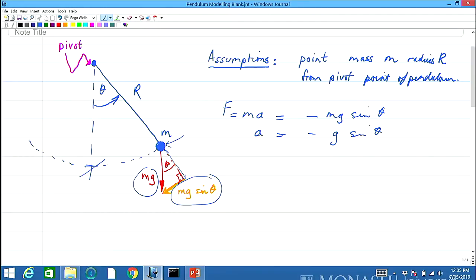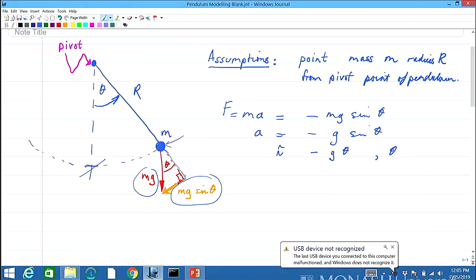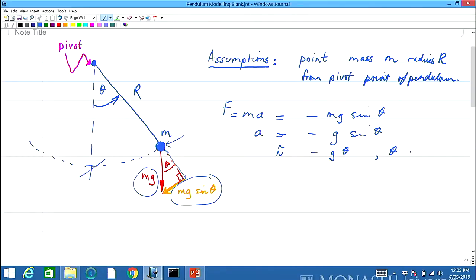So therefore the acceleration of that mass is minus g sine theta, and we can approximate that in practice by minus g theta, where theta is small. All right, so for our purposes, small is less than 20 degrees, thereabouts, typically, and the errors will be quite small in that regard. We can actually work that out later on. So we can then model this acceleration by looking at the...